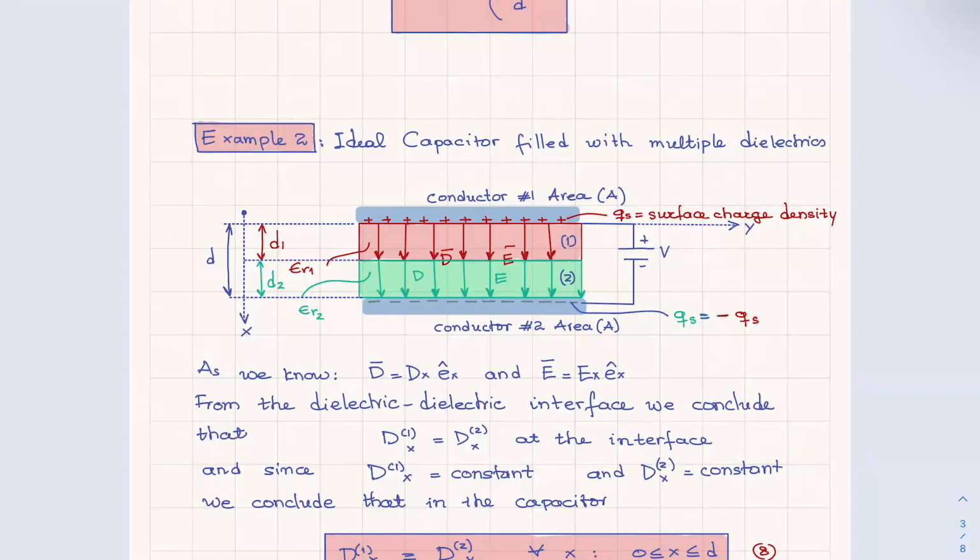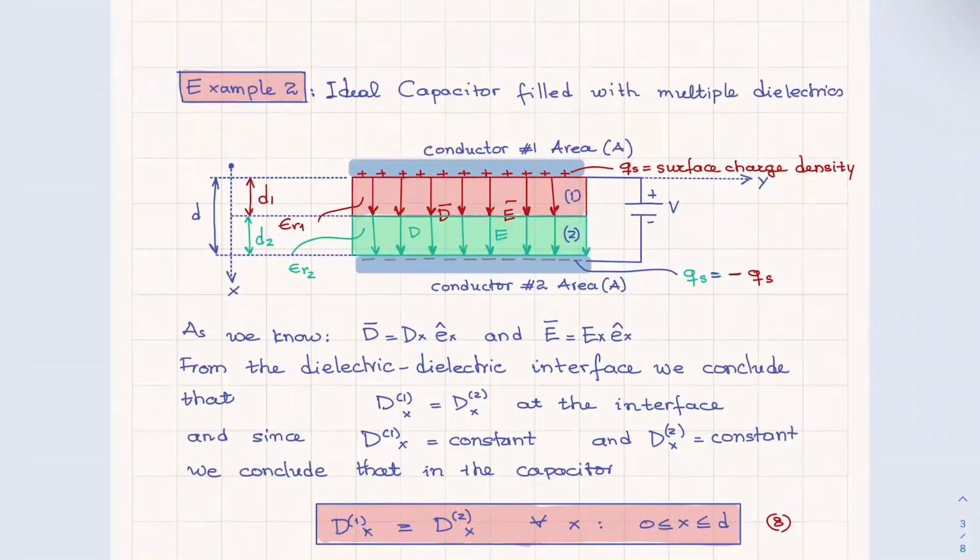And then you use two conducting plates, and you want to calculate the capacitance. It might be a desired capacitance, might be a parasitic capacitance if there is just an overlap. But in the desired capacitance, obviously, as we discussed right now, you're going to have two different media, because silicon oxide and silicon nitride have two different dielectric constants. So of course, in that case, you will have to use a different formula from the previous one to characterize the capacitance. And that's what we are going to try to learn.